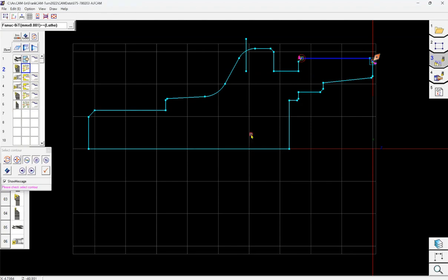When the contour changes up and down, a message pops up to ask you which way you are going. If you want to skip the groove, you click the line here. It will connect the contour directly and keep selecting the contour according to your pictures automatically.